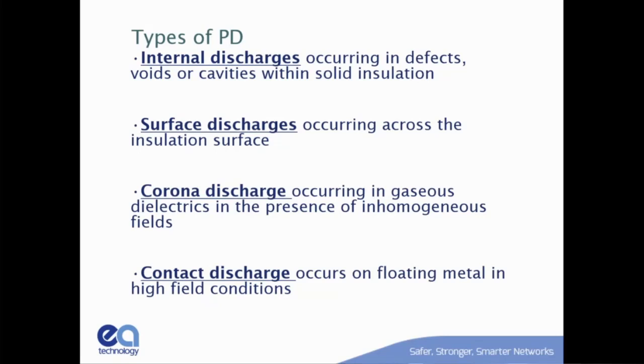Now, surface discharge is the most common. This is where you see the tracking, the treeing, the white powder, the cracking of the surface. All that is where the discharge current is traveling on the surface of the insulation. And that's real common. It's the fastest moving. It is related to the environment, to humidity and pollution. Fortunately, it's the easiest to find and the easiest to correct. So that's got good and bad.